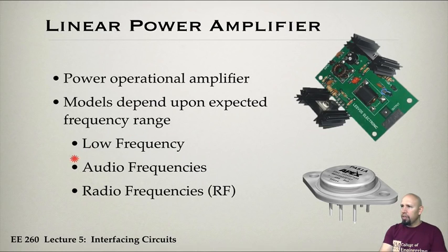Low frequencies, for example, you can control a motor using a power op-amp, and that's very common instead of an H-bridge. But that's low frequency. In other words, in this case, you're not actually doing the H-bridge. You're actually supplying a variable voltage. Okay, and so that can also work, and that can be used for control. And in fact, in closed loop controls, that's often desirable, is to use a power amplifier.